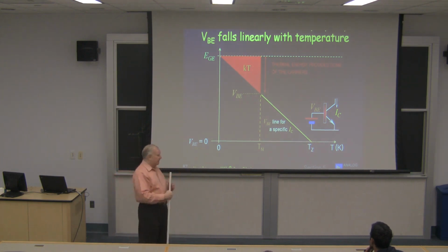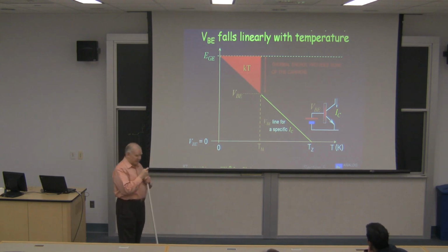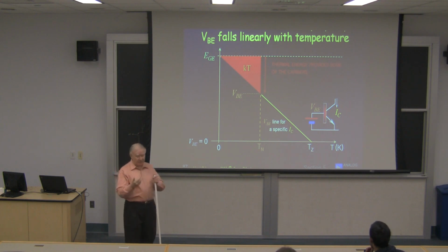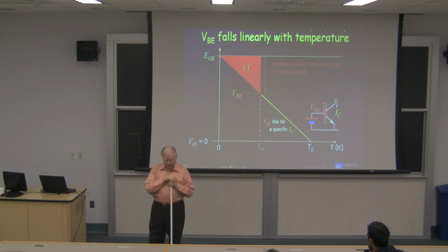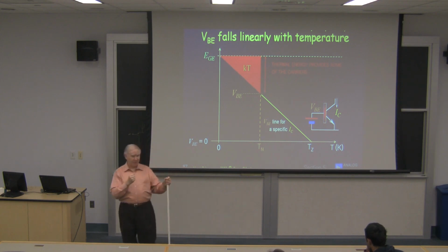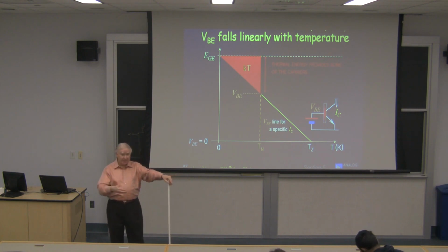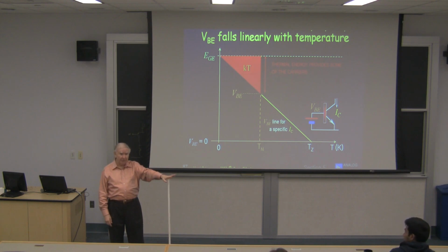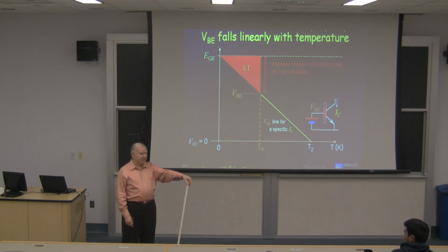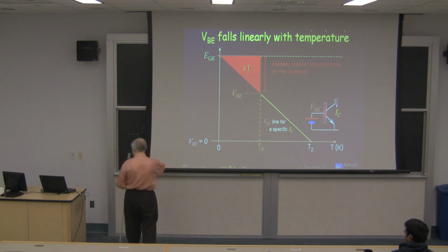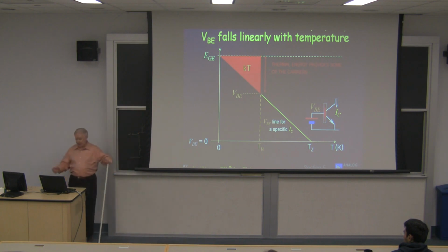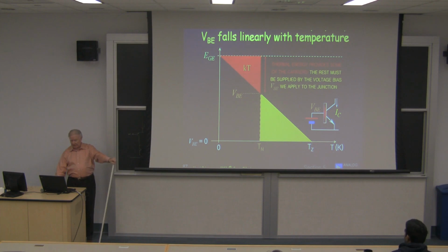And it's pretty high, depending upon the size of the device, but it's so important in practice, believe it or not, that in an electrometer logarithmic amplifier, of which we have several now in the catalog, we measure currents down to a picoamp. When a picoamp is applied to the logging transistor, the VBE actually goes negative at high temperatures. It behaves like a depletion device. You've got to actually pull the lever back on the base emitter voltage because, you see, it's very simple. The I sub S is so big. I sub S has now exceeded the 1 picoamp you're trying to measure. So VBE can go negative, and that's not a joke. That's a reality. You don't often come up against it because it only happens at low currents and high temperatures, but it does happen. So as I say, that's the rest that we have to apply.